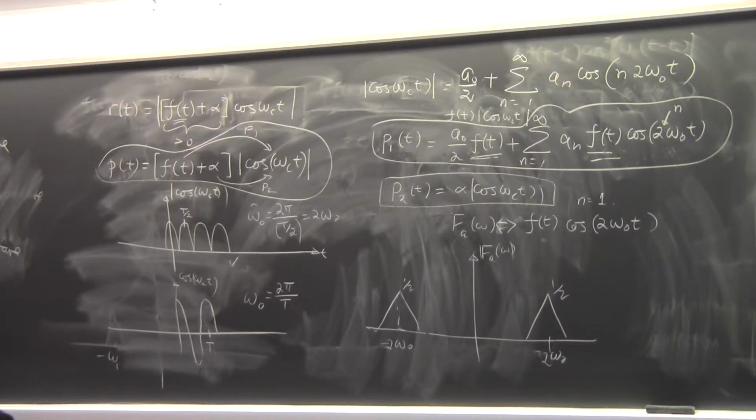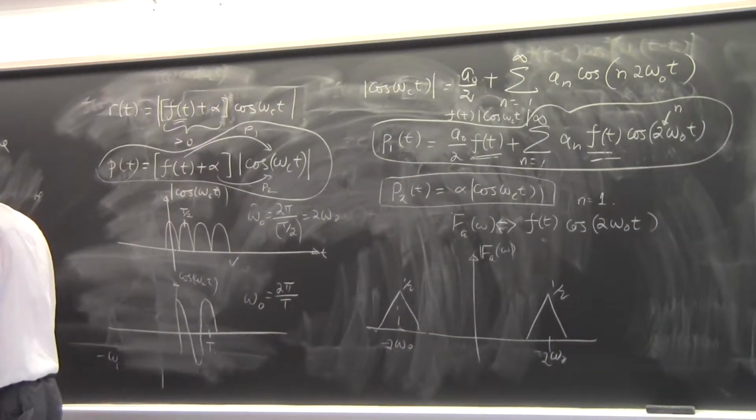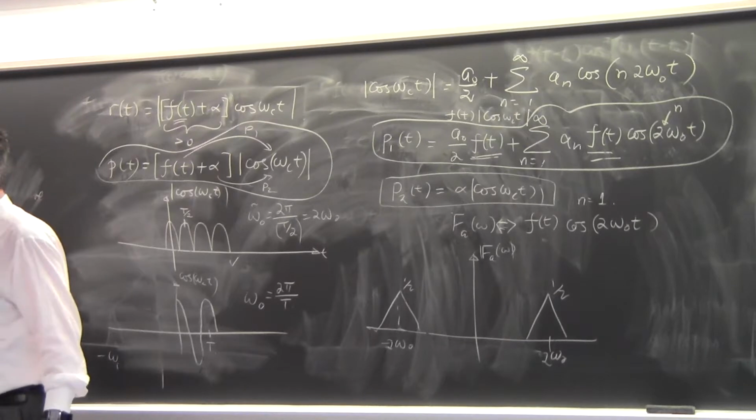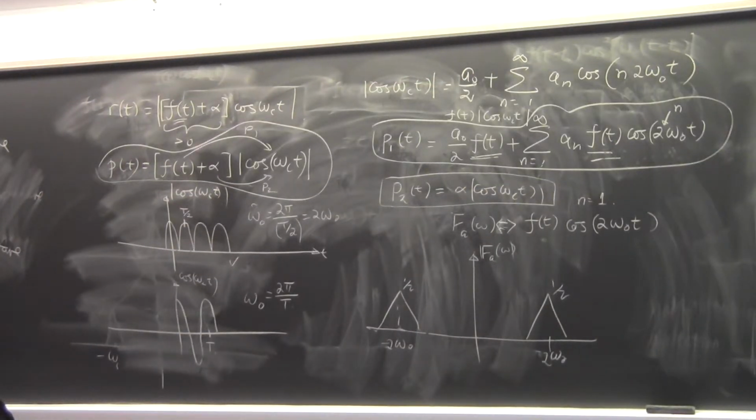and you don't need a coherent detection. You don't need to adjust something that is properly time delayed and properly having the same phase. It's a very cheap detector. And you can even do it this way. This way is even cheaper than this one. This one needs 1 diode, this one needs 4 diodes. And if you do it that way, then you don't have exactly this signal, but a signal that looks like this.